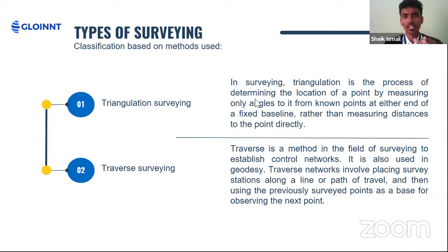With the help of that, you divide the area into multiple triangles, and you get the area of a single triangle. While combining all the data, joining the areas of all the triangles, you will easily get the total area.